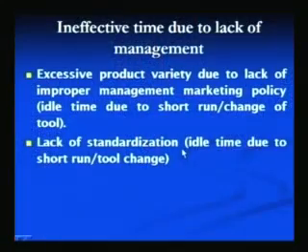The lack of standardization: if the organization is manufacturing a variety of products, that will lead to idle time due to the short runs and the small volume of production, which will require a frequent change in machine tool setting. And the midstream design changes: if the product which is being manufactured is not developed properly before going for production, then it may not be able to fulfill the requirements of the market or of the customers. So, frequently, due to the failure of the product to satisfy the market needs or the customer needs, it is required to change the design of the product in between the production process.